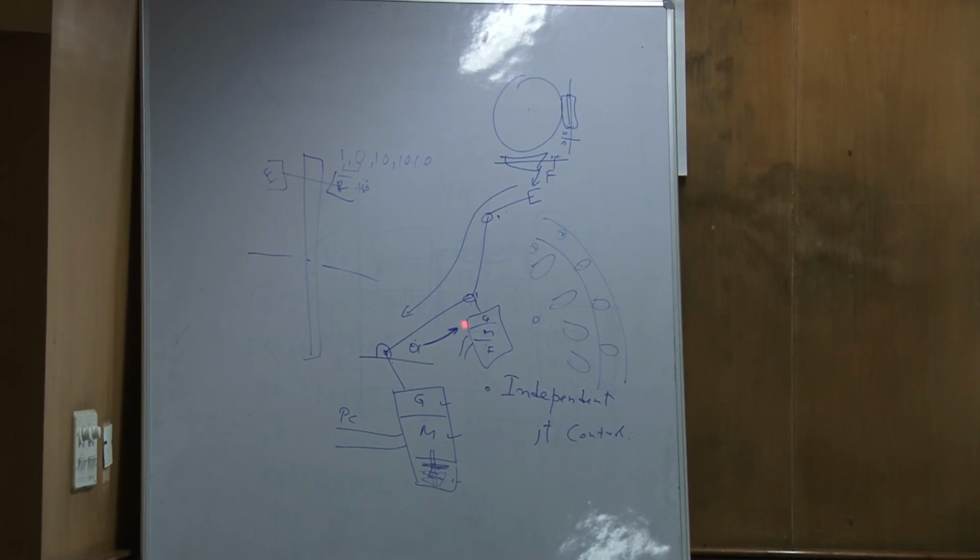So one of the experiments is you have a point there, and I want to go. Suppose I'm here and I want to go to some other point. Then doing inverse kinematics, I can find what is the corresponding angle, and then whatever is the corresponding angle, I can see the equivalent PWM for that angle, and then give it there, and it will exactly go and stop there. Okay. So I can actually do motor control very easily without getting into PID controller design and all that, simply by controlling the microcontroller through a servo motor.